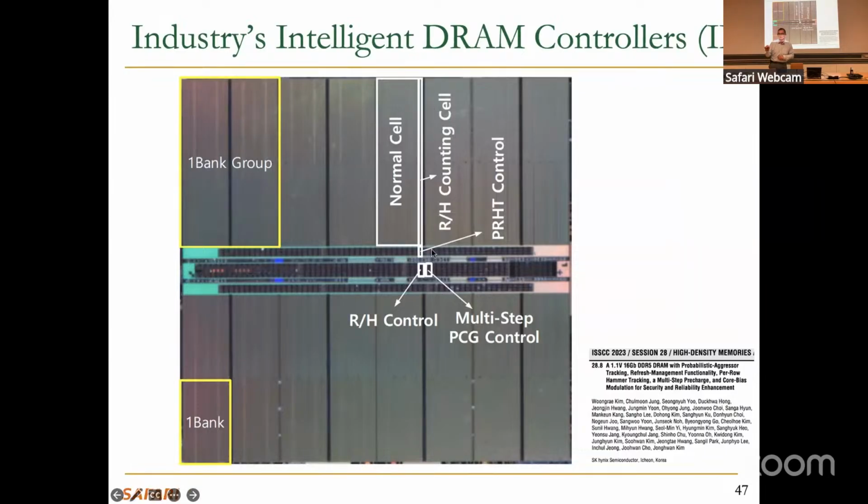If the DRAM chip gets an activation, you have a row, you have an activation counter associated with each row. So you waste some space in DRAM to store the activation counters. And with every activation, the DRAM chip automatically increments the counter associated with that row. And at some point, if the activation count is greater than some threshold, which they don't disclose, of course, or they don't disclose how to calculate, the DRAM chip takes an action, which is refreshing adjacent rows. They don't talk about how many adjacent rows, etc. So these things matter. That's important.